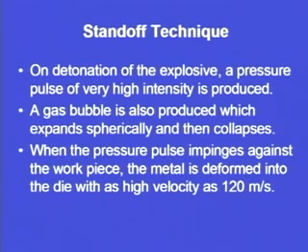So, a rule of thumb or some particular value has been quoted, that is 120 meter per second. We can see that the explosive is detonated, a pressure pulse is created, that pressure pulse impinges against the workpiece and the metal is then deformed at a very high velocity. That velocity may be to the tune of 120 meter per second.